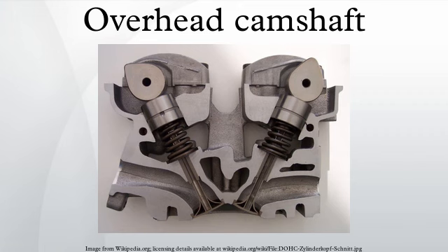In the early 1980s, Toyota and Volkswagen Group also used a directly actuated, SOHC parallel valve configuration with two valves for each cylinder. The Toyota system used hydraulic tappets, while the Volkswagen system used bucket tappets with shims for valve clearance adjustment. Of all valvetrain systems, this is the least complex configuration possible.